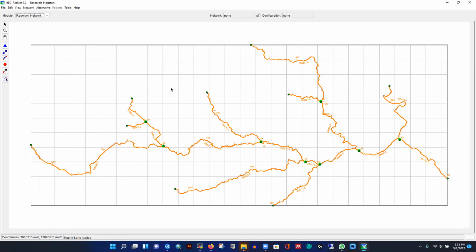So here what I have to do, I have to connect this node with this node and everything using our reach tool. Here we can see we have a tool called reach tool, because if you put any inflow there, this inflow needs to be carried using any routing method. If these nodes are very close, then you don't need any routing.